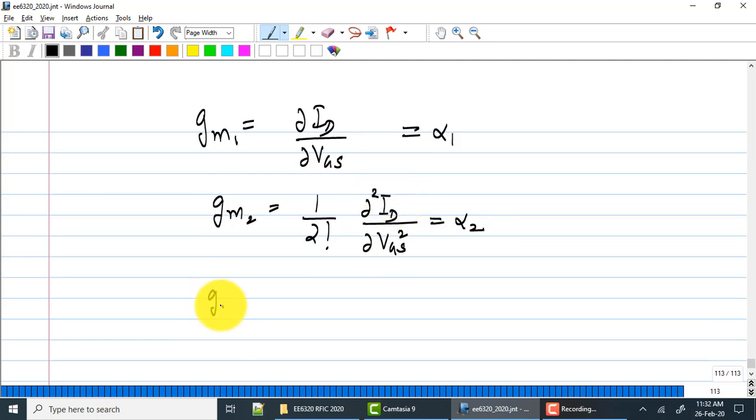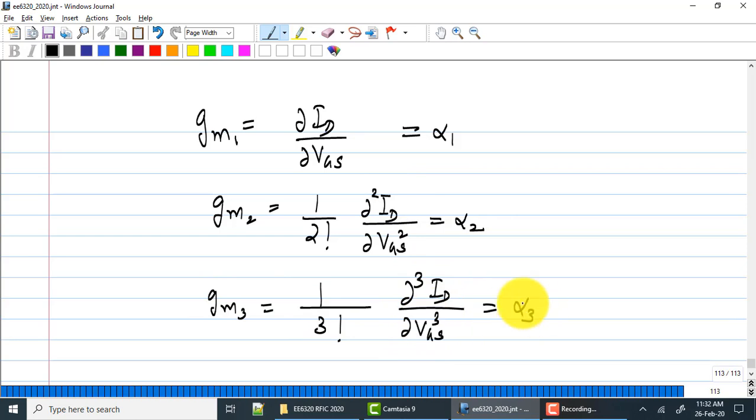I am saying they are equal to, but remember in your LNA, we are assuming that all passive components are 100% linear. What do you think the IIP3 of an inductor, resistance and capacitance are? They are supposed to be infinity. In reality, there will be some nonlinearity. If you take a resistance, you can measure its IIP3. Your assumption of the resistance, inductance, capacitance being 100% linear will break down at about 2 orders of magnitude larger IIP3 compared to your transistors.